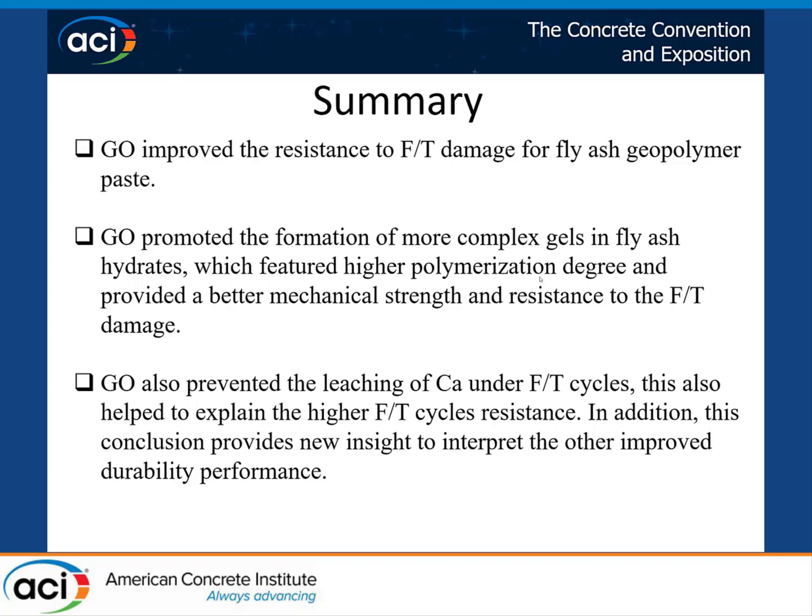Right. Zhipeng, if you allow me, I will try to answer that. First of all, the freeze-thaw durability maybe was not remarkable, but the test samples were really small. They were cement paste or geopolymer paste, and they didn't have any entraining agent. So that's why you don't see a whole lot of rapid freeze-thaw cycles.